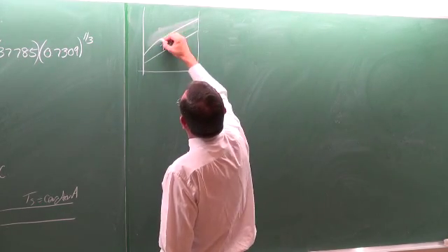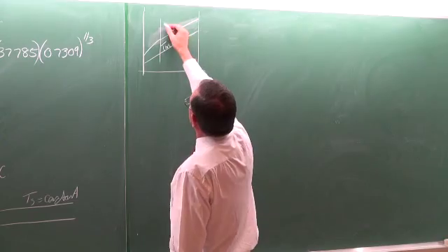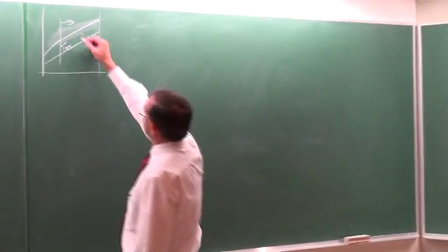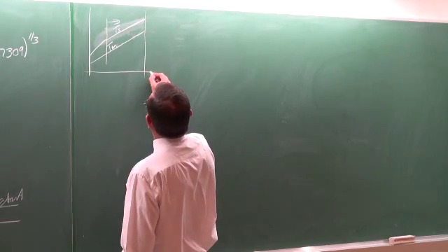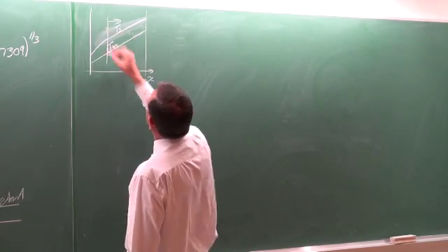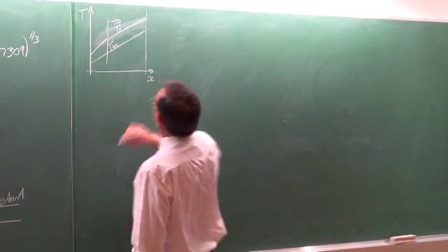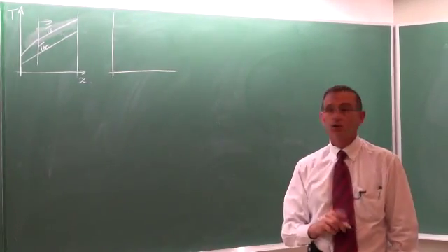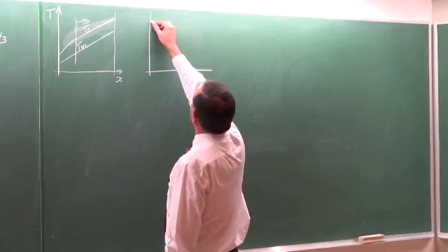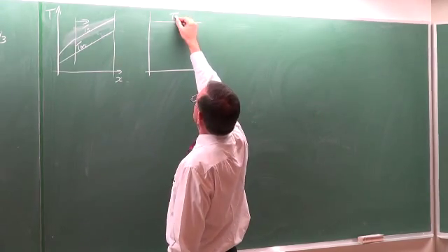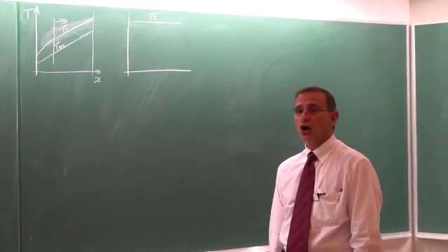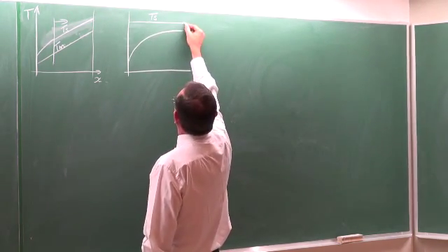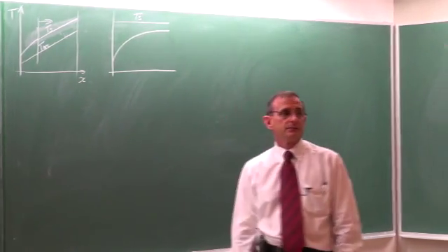After it has been fully developed. Okay, so that is the surface temperature, and that is a function of x. For the constant surface temperature case, the surface temperature is a constant, and then we've shown that the temperature distribution does something like that.